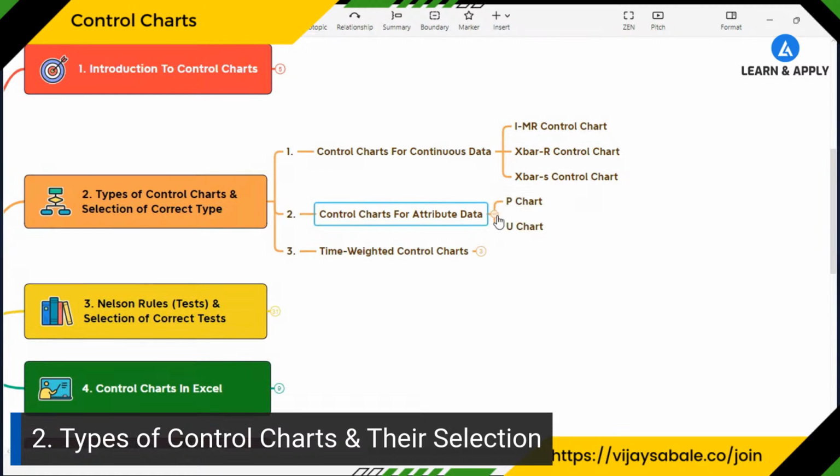Now let's say you have attribute data, then the selection criteria is what is our area of interest. If you are going to track the number of defectives or proportions, then we are going to use the P chart. P stands for proportions. Or if you want to track the defects per unit, that means one unit can have multiple defects, then in that case, we are going to use the U chart. Of course, it is based on whether your subgroup size or sample size is constant or not.